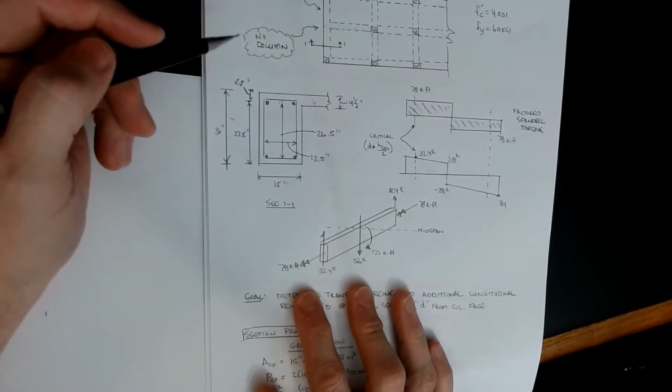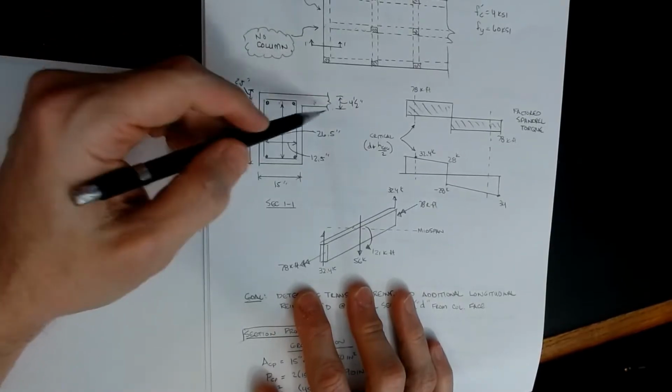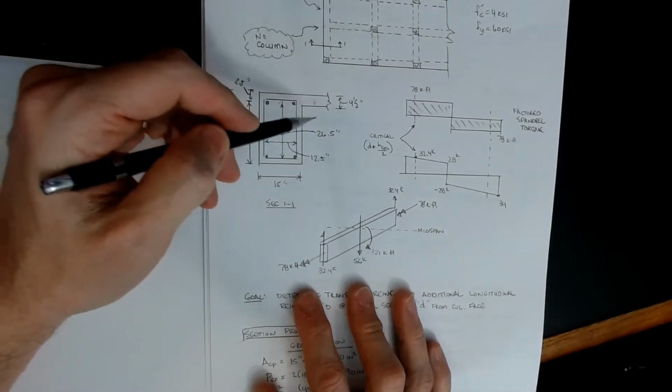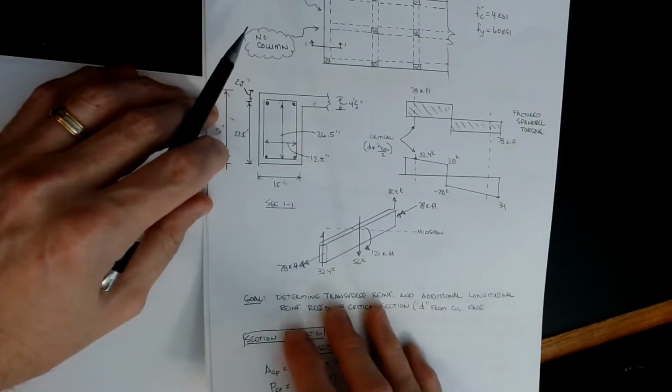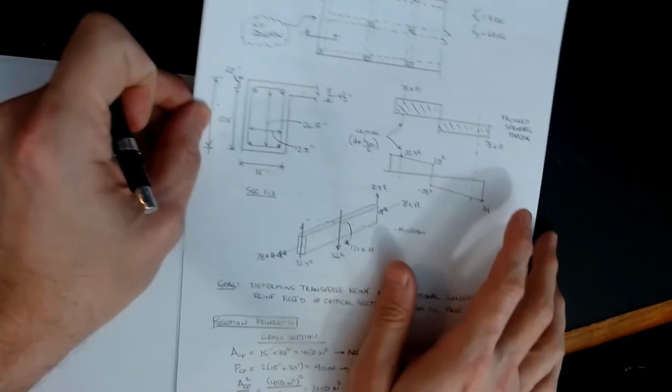Okay, and I can accomplish that a couple of ways. I could put an expansion joint between the slab and the beam. Or we just, again, this thing's 30 inches tall versus 4.5. This isn't going to provide much. It'd be a few percent, but not a whole lot. All right, so that's our cross section, and we'll come back to using that here in a second.